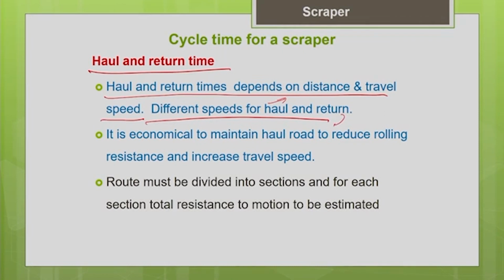So, it is very important to note that we have to maintain the haul route. We have to spend some effort in maintaining the haul route of the project site. You have to maintain it either with the help of a grader or a bulldozer. We also have to maintain the haul route using water trucks.